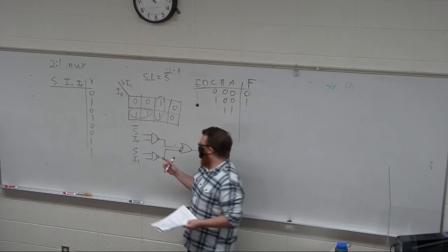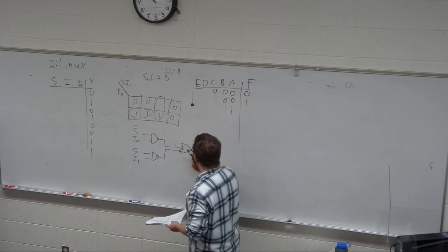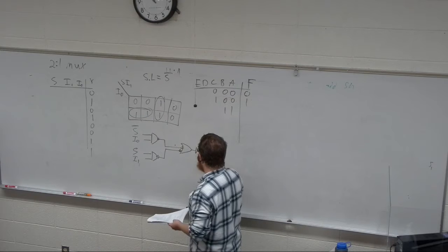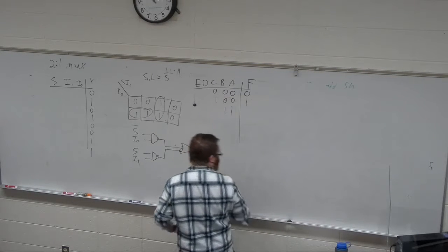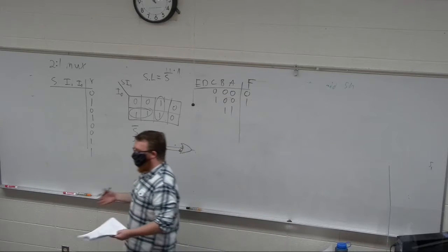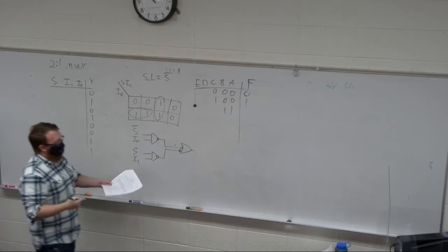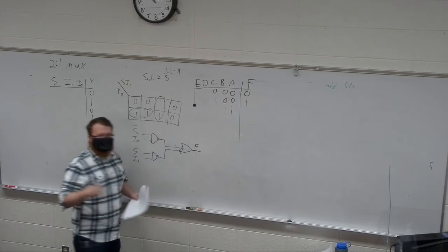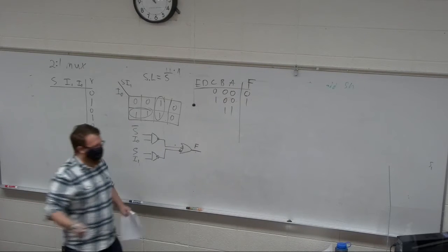Except for on the outputs, occasionally you will actually see it be like F dot low and you'll add an inverter here, right? So that's the thing to be aware of, and this could happen. You could design a circuit for F and then realize that, oh, this needs to be active low. I care about it at the output most of the time. So this is F. If I need F dot low, another way of saying that is F bar.